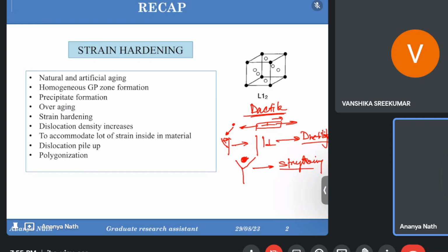But in our case, for cross slipping, we want the dislocation to move and get piled up. So for that case, we don't want this stacking fault width to be much more. We want this to be little so that the SFE will be high, and we can go for the strain hardening for non-heat treatable alloys. So this stacking fault phenomena is a bit different and opposite for both the cases, for heat treatable and non-heat treatable alloys. Is it okay, or do you have any?